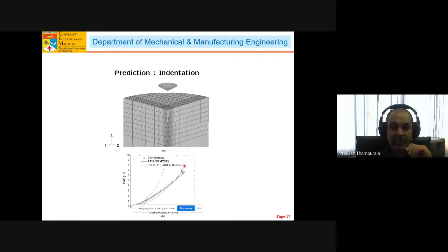And you can clearly see that the experimental response is actually quite well predicted by the polycrystalline simulations. Yeah? We've used the Taylor model in this case, okay, because the deformation here is basically non-homogeneous. So we have to use some kind of homogenized response at the Gauss point level or at the finite element level, okay. And we clearly see the effect of twinning here.